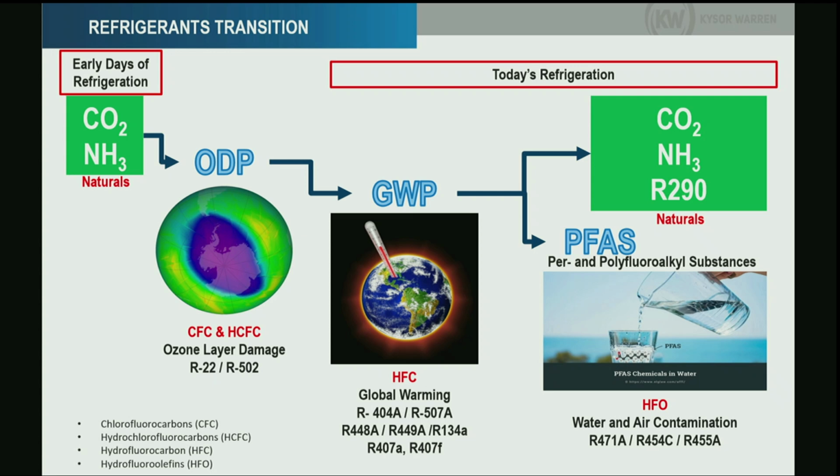But even though we have those HFO refrigerants, we still have the natural refrigerants. CO2, ammonia, and propane now are refrigerants that we can handle better than we had before. And those are, again, natural refrigerants that do not damage as much as the chemicals. Also, they are efficient refrigerants that we can use to produce refrigeration for the supermarkets.